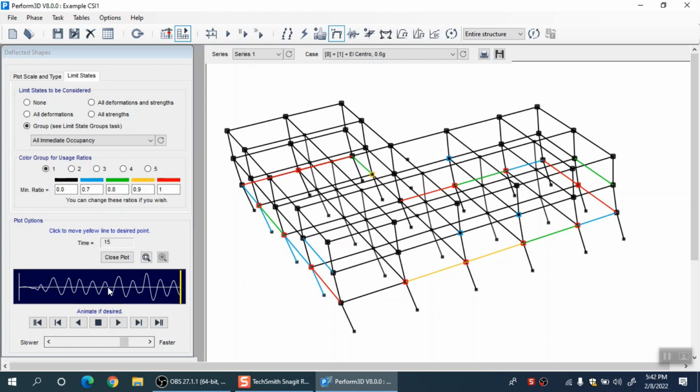So, the purpose of this whole exercise is not to actually design or keep the capacity ratio below 1, the purpose is the real performance evaluation, right. So, we want to simulate the damage of the building in its current design. We want to see how this design is going to perform under a certain level, right. So, no factor of safety, no load factor. Load is not increased by a factor, load is applied in its real condition. So, all those code factors are not applicable here.